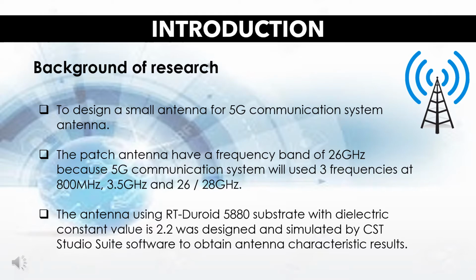The antenna using RT-Duroid 5880 substrate with dielectric constant value of 2.2 was designed and simulated by CST Studio Suite software to obtain antenna characteristic results.